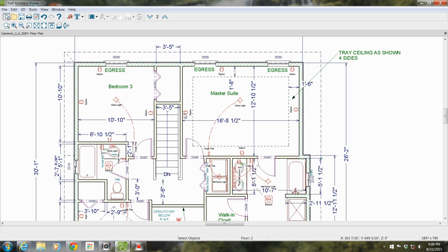You see your outlet, your windows, both of those are egress. Just to keep some symmetry, you only need one, but just to keep some symmetry on the outside of the house, we made these the same, because this one has to be an egress, because this is only, I know I hopped through the wall, sorry, but this has to be an egress because it's the only window in this bedroom. So to keep the symmetry on the outside of the house, we did the same size windows here, both egress.